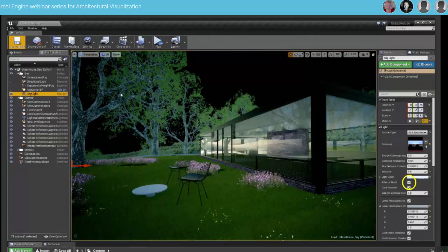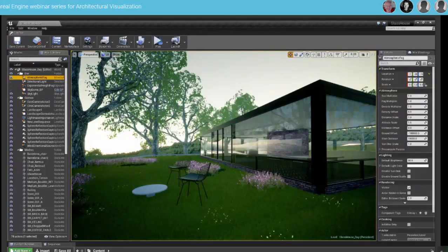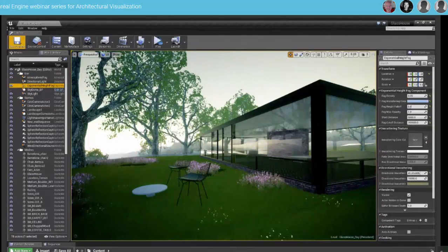We tend to have very flat shadows with a very small amount of detail, and leave the reading of the information in the shadows to the imagination a little bit. So this is the effect I was actually looking for. If I move on, I've turned on my atmospheric fog, which gives me a very definite illumination of the sky here. Then the exponential height fog is going to cover the geometry between the horizon and my scene.